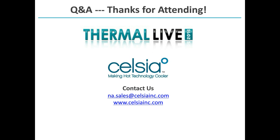Got it. Okay. And a question from our friends over at Intel. Do vapor chambers allow bends in the XY plane? Well, you can see from the pictures that we can bend them in the one plane. It gets much more challenging to bend them in the other plane. If I have a relatively long vapor chamber, I can do some bending before I flatten it. So it is possible. It's just not very common to bend the vapor chamber in the long beam direction. So you can bend them in the thin direction, but not in the width direction.